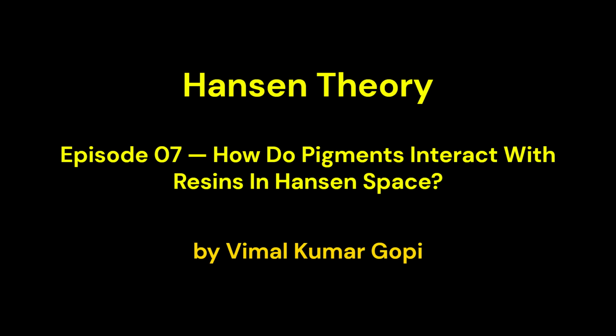Now, let's tie this back to previous episodes. Hansen theory for solvent design is only part of the picture. Polymer behavior defines the solubility sphere. Pigment interactions define additional constraints. Additives and dispersants fine-tune compatibility. Scale-up and environmental conditions test the robustness of your design. This is a multidimensional problem, and Hansen theory provides a framework to manage it, not a simple formula to follow.